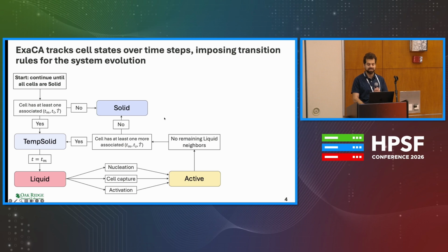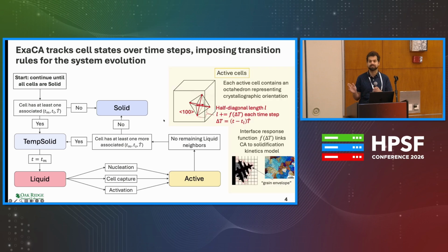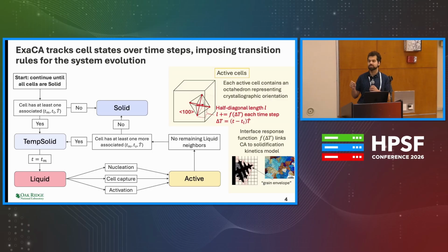So you can immediately see here that these active cells are only a small portion of your domain because you're melting this with a laser. Your parts are pretty big. You're really solidifying a small region on a given time step relative to how big your parts are.